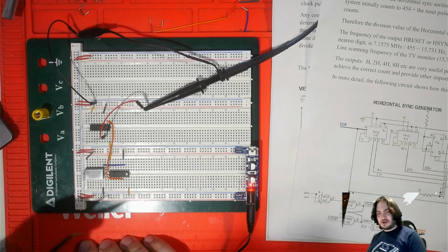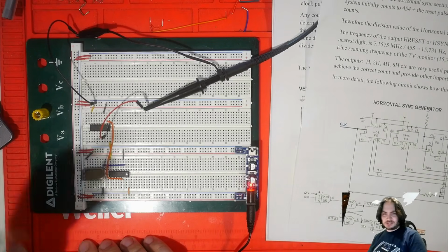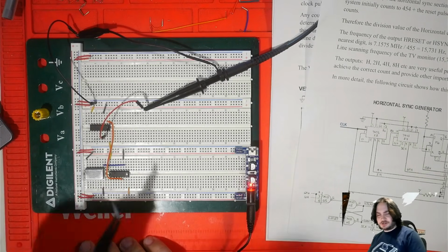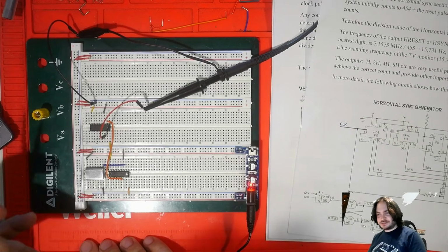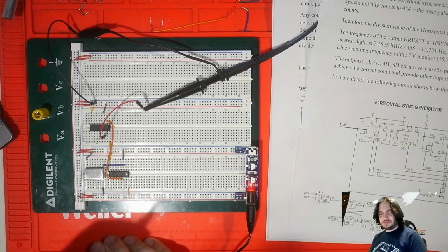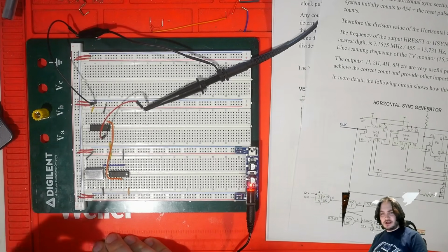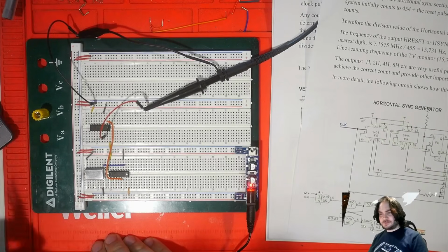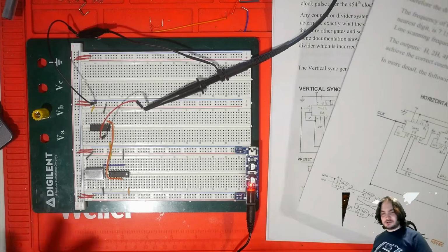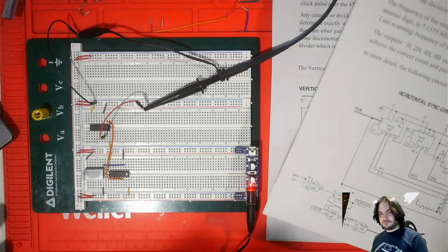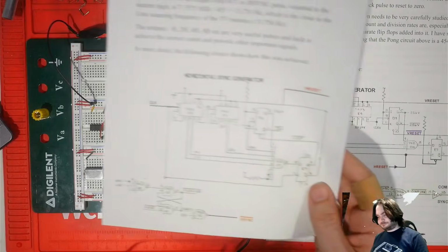And they're going to have numbers based off of the frequency division that is occurring from the original clock. So you've got 1H, 2H, 4H. These are a half of, a fourth of the original clock. And we're going to combine these together to count to a specific number and then reset the chip.